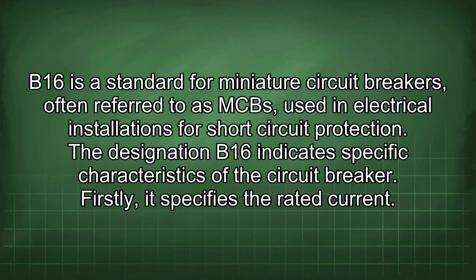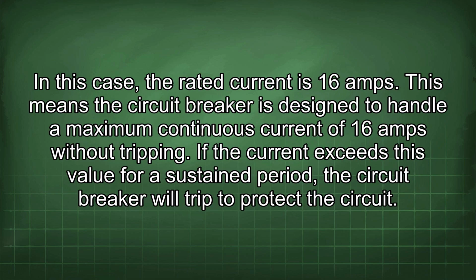B16 is a standard for miniature circuit breakers, often referred to as MCB, used in electrical installations for short-circuit protection. The designation B16 indicates specific characteristics of the circuit breaker. Firstly, it specifies the rated current. In this case, the rated current is 16 amps.